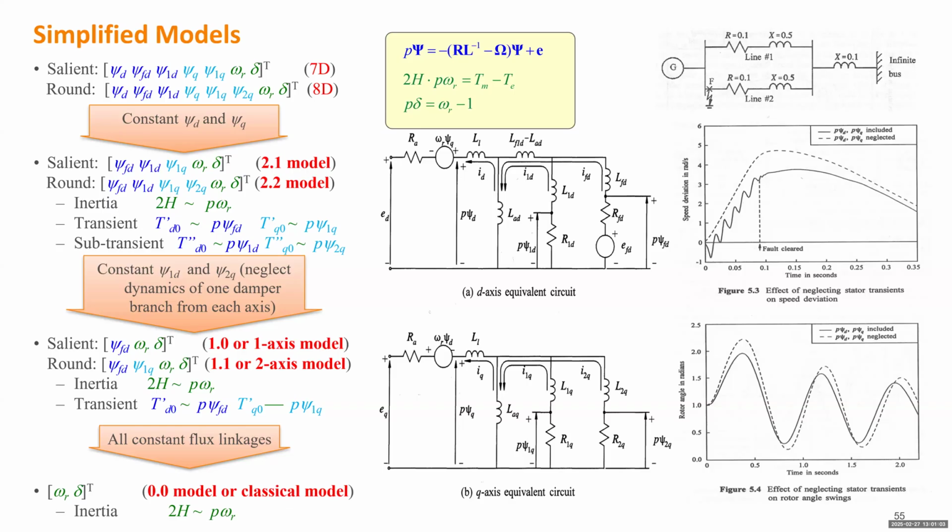Okay, in some other fields, if we study protection or the design of generators, they definitely model the generator more accurately. Similar to what we derived based on the voltage equation and flux linkage equation, you can always go back to those equations. If you do electromagnetic transient (EMT) studies or simulation, you will need to go back to those equations, because the models here are not accurate. Don't use those models for EMT simulation, unless you only want to do an approximate study.